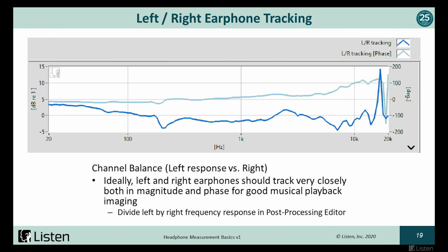Anyhow, moving along. So if we want to have good imaging, we want to have good left-right channel balance. And again, ideally, we want a flat curve at 0 dB, and we want a flat phase curve, ideally at 0 degrees. So with this particular headphone, and this is where in-ear headphones, you've got to be really careful with how far you insert the left earphone relative to the right earphone.